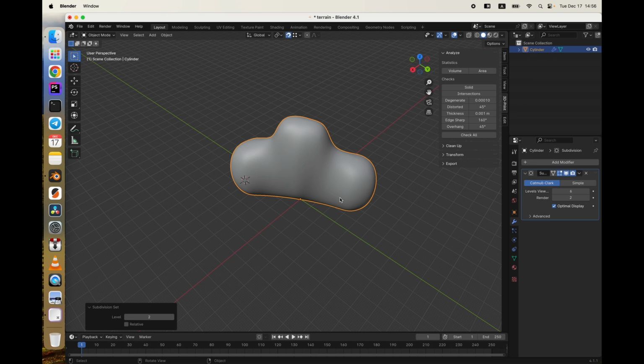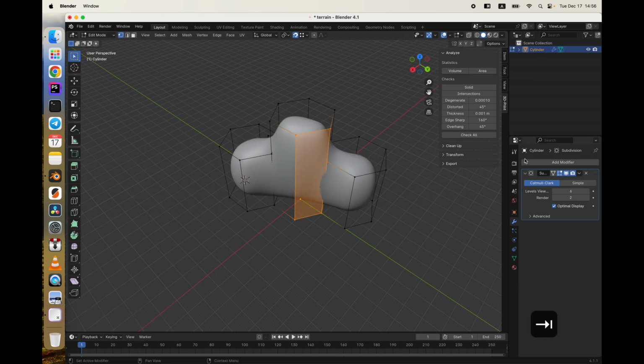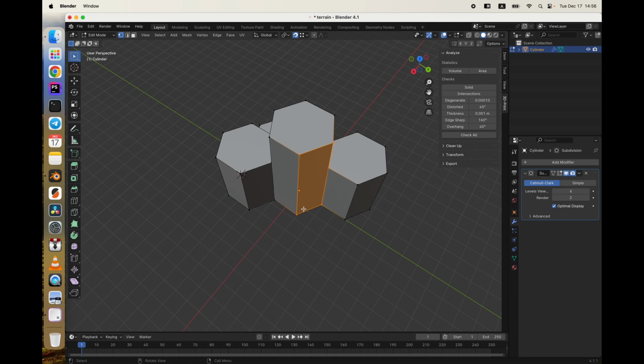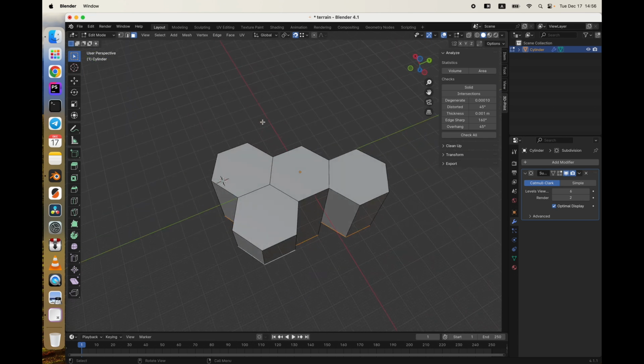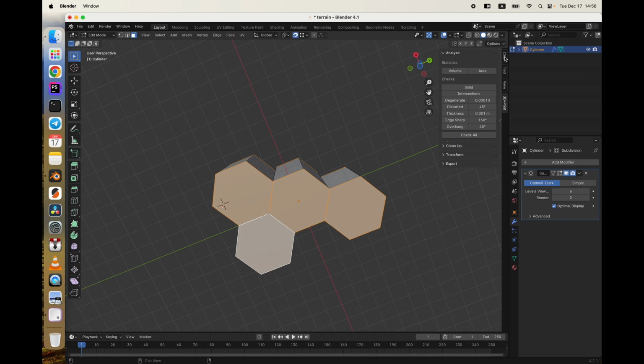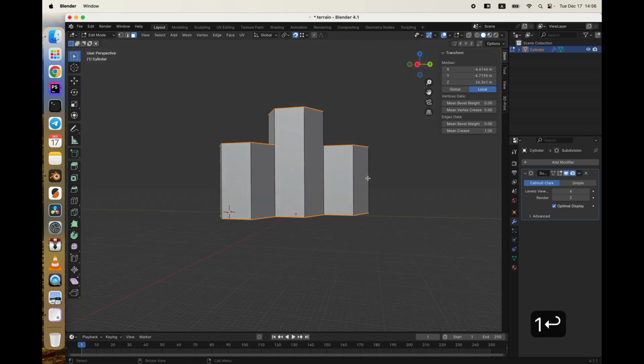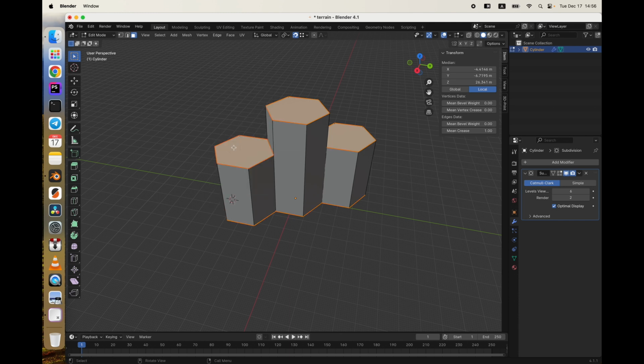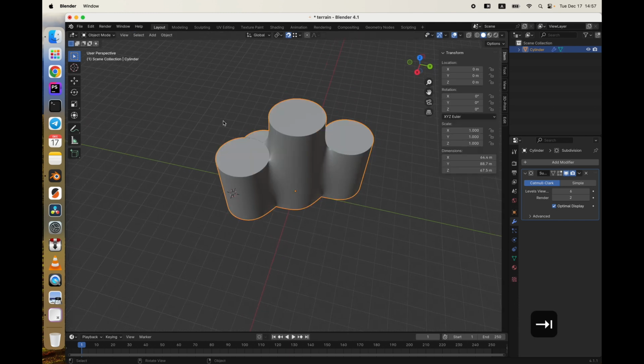Let's fix that. Let's go into the edit mode. Let's hide our modifier in the edit mode, pressing here. And let's select all the horizontal faces that we have. Press 3 to face mode selection. Select these faces. And the bottom ones too. Go to the Item tab, add an edge crease. Set it to 1, its maximum value. And we will also add a seam here. We will use it later. Mark seam. Let's exit edit mode.